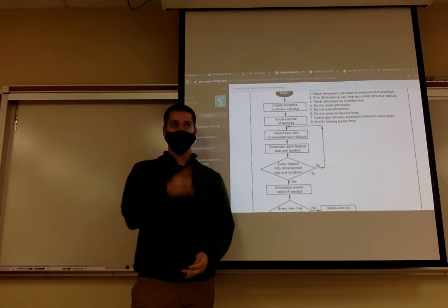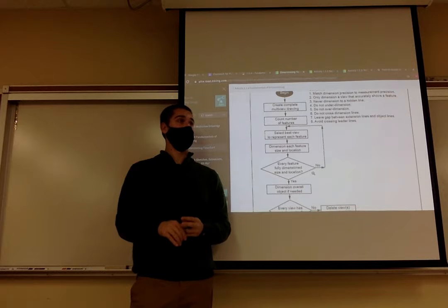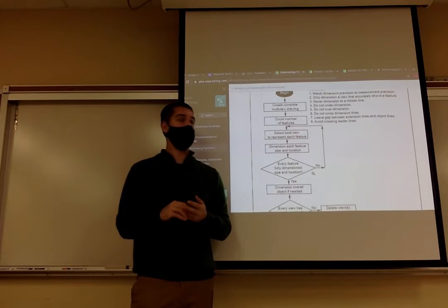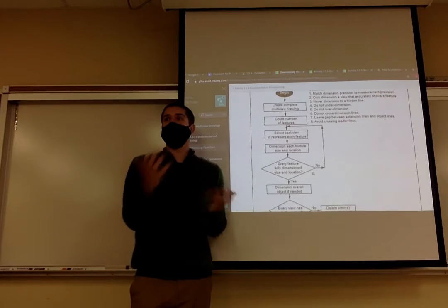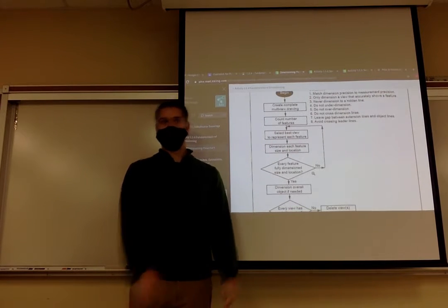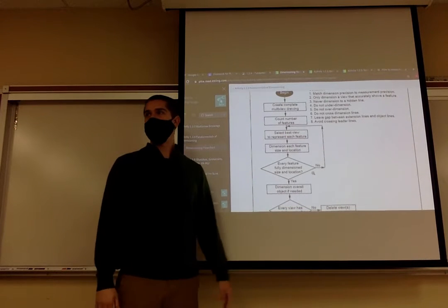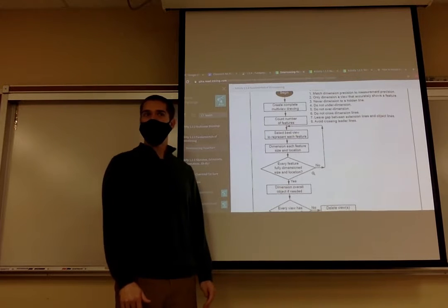How deep is it? The center. Yes, that's another piece. We'll get to that when we actually use the hole command. The depth of the hole can be dimensioned and communicated. That's a good point. But the main thing is the location. I tell you I've got a 1 inch hole. It's here, but where? Is it 1 inch from the end? Is it in the middle?